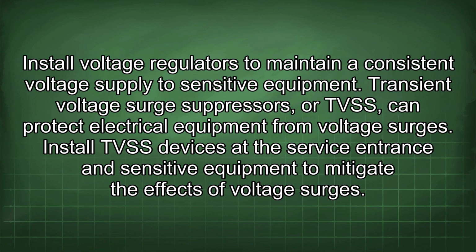Transient voltage surge suppressors, or TVSS, can protect electrical equipment from voltage surges. Install TVSS devices at the service entrance and sensitive equipment to mitigate the effects of voltage surges.